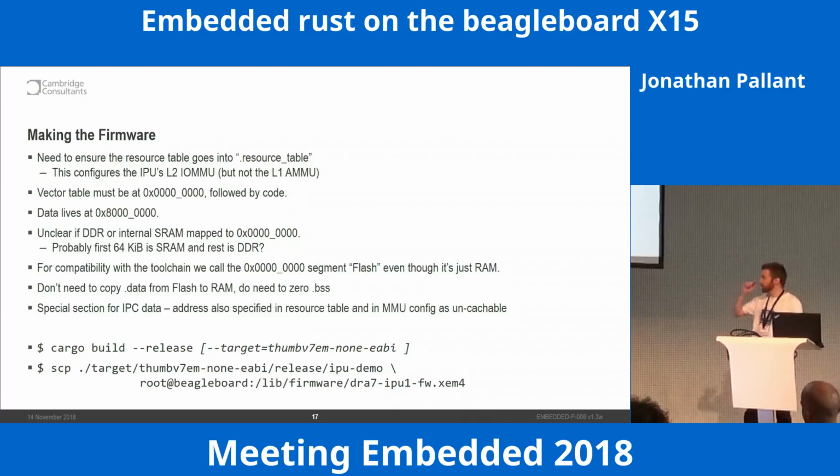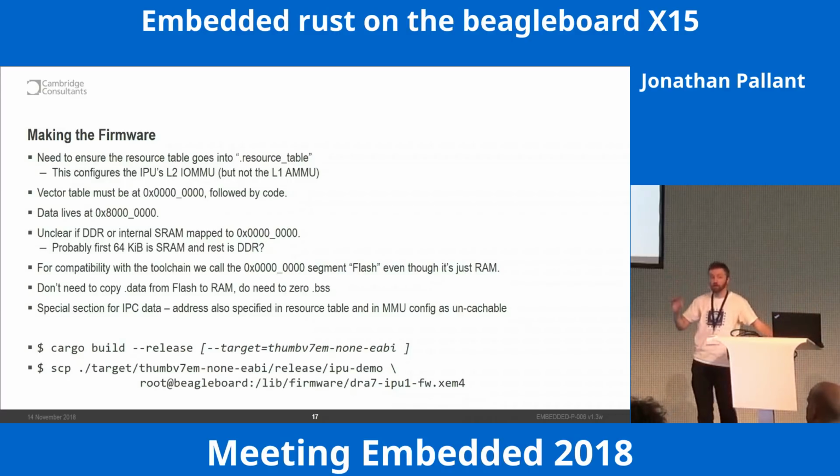So there we go. There's another top takeaway tip for you. If you've got two CPUs sharing some RAM and exchanging data, turn the caches off for that particular region.